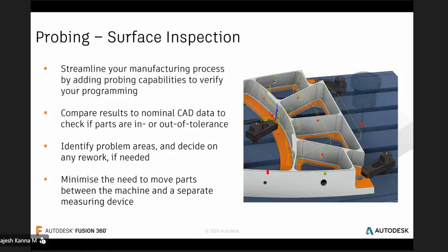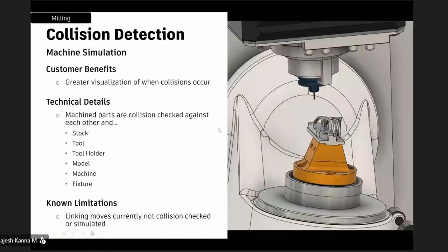If it is undersized, you have to get back to the CNC machine and remachine it. Now that workflow is very complicated and resetting is also very difficult actually. So in this case, once you machine, you inspect your part then and there. If it is good, you can move the part. If not, you can remachine it in the CNC machine itself actually.